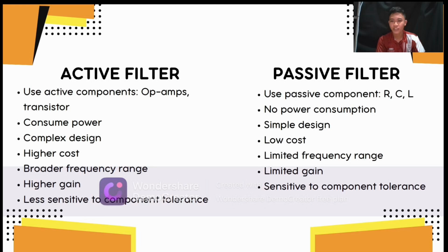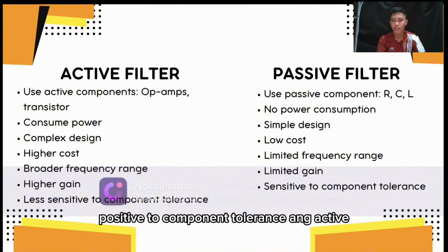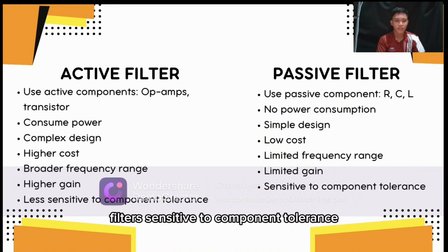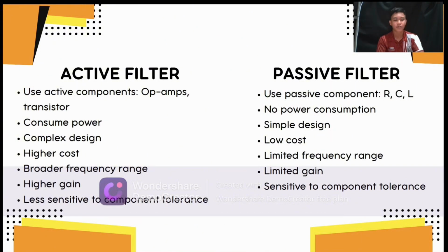Broader frequency ranges in active filters, while passive filters have a limited frequency range. Active filters have higher gain, while passive filters have limited gain. Active filters are less sensitive to component tolerance, and passive filters are sensitive to component tolerance.